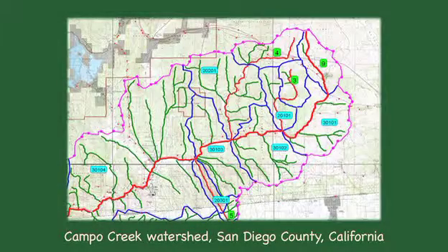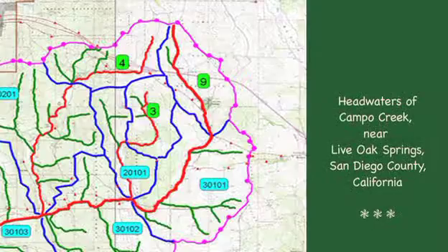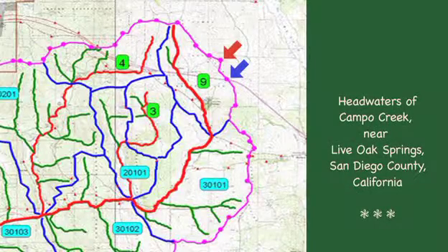The catchment divide follows the peaks and saddles of the topography. The collection of peaks and saddles determines the physical location of the catchment divide. Because of subsurface flow, the topographic divide may not coincide with the hydrologic divide. In the absence of the detailed groundwater evaluation, the topographic divide is usually taken as the hydrologic divide.